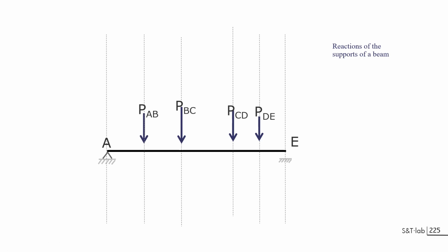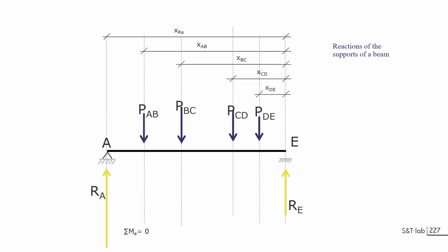So you have three components of forces. If you are trying to solve the system, you will use the equation linked to these three possibilities of movement, for bending forces, for example. This procedure drives you from a moment around the point here to define what will be the reaction force E on the left side, considering the respective contribution of all these forces. That can be done easily with graphic statics. I will show you about reaction forces.